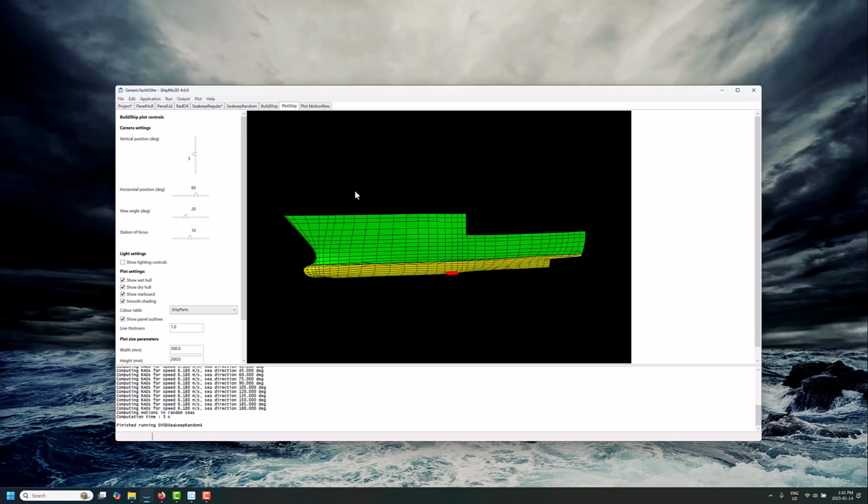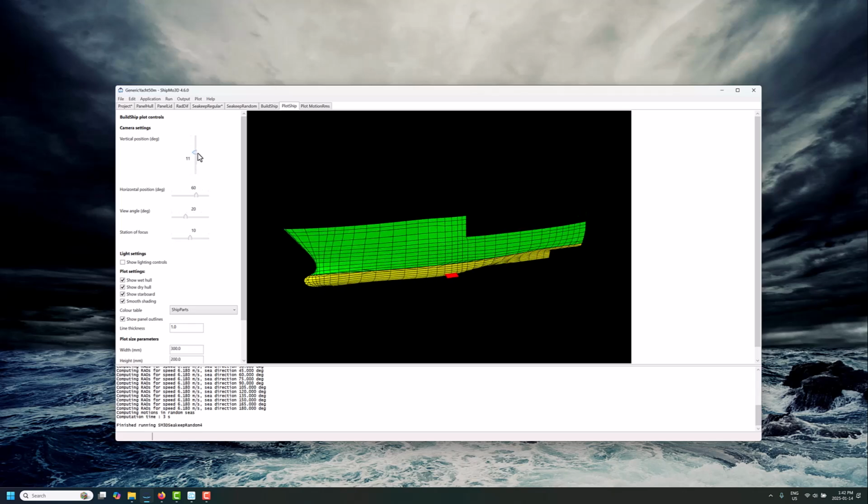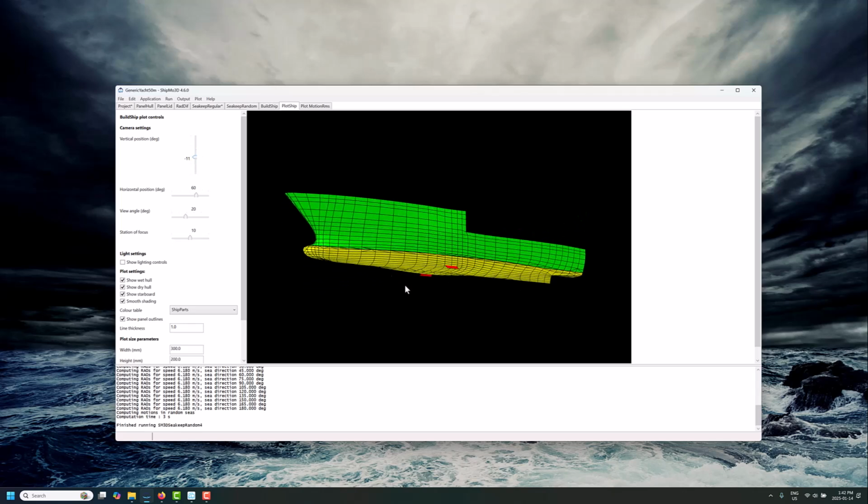Let's turn the conversation to what it is doing and how it helps. In the seakeeping calculations, seakeep regular and seakeep random, these are all frequency domain, so everything is sinusoidal and linearized, but the forces are highly nonlinear. So what's happening behind the scenes is an equivalent damping coefficient is resolved in an iterative process in the solution process for solving the system equations of the ship dynamics.